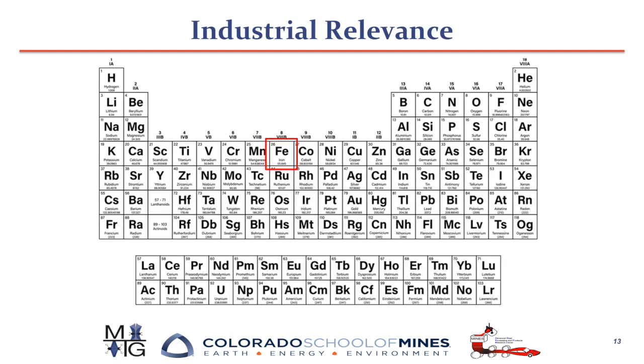Let's say I have iron and I would like to alloy it with carbon, which I know is a cohesive enhancer. Boron is also a cohesive enhancer and a common alloying element, whereas phosphorus is an embrittler at the boundaries. Using this technique, I can study the individualistic segregation behavior as well as co-segregation behavior at the boundaries in different concentrations of solutes. Not only interstitial solutes, I can also study substitutional solutes like chromium and molybdenum by way of understanding what differences they impart in the electronic structure as they segregate to the boundaries.